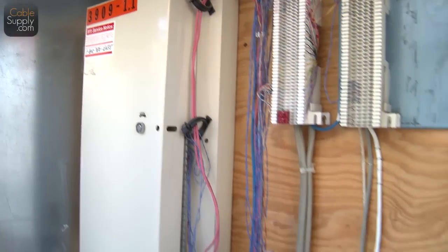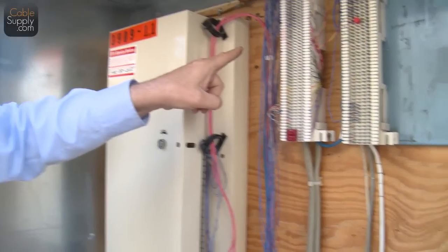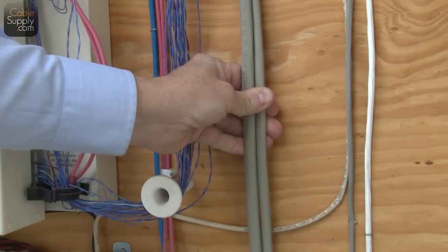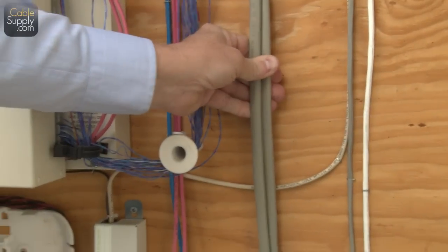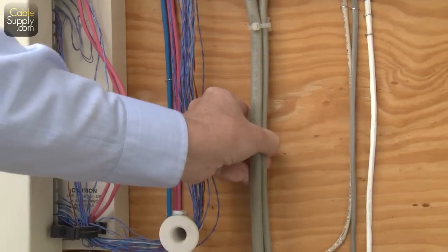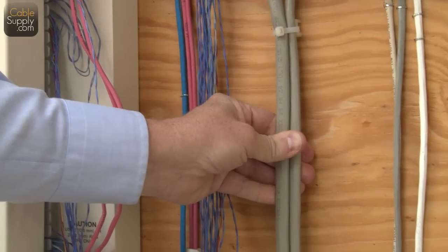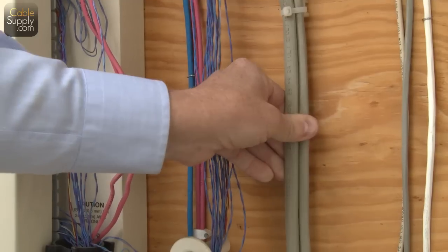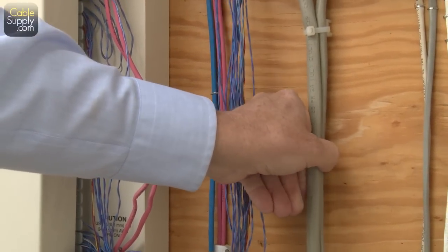The best thing to do is always feed your house cable up from the bottom, always feed your cross connect across the top. This is the house cable. It's called house cable. It's actually not a house, but it's the cable that goes into the building. So this is owned by the customer. So this is customer provided equipment, and this is the responsibility of the customer. Of course, you could always pay the phone company to troubleshoot it for you if you'd like, but this is the responsibility of the owner of the building or the occupant of the building.